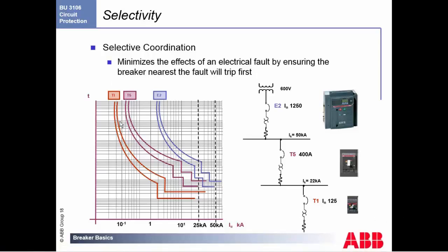We show right now 2 reds, 2 curves for each one, noting that on the E2 you can set this curve up for it, or you can set this curve up for it. So typically what you'll see is you'll choose one curve over here, which means that if I'm sitting at 1 times my nominal current, it will never trip at the main breaker, it's going to trip at the smallest breaker. Again, selectively coordinating so that I'm only popping this little branch.